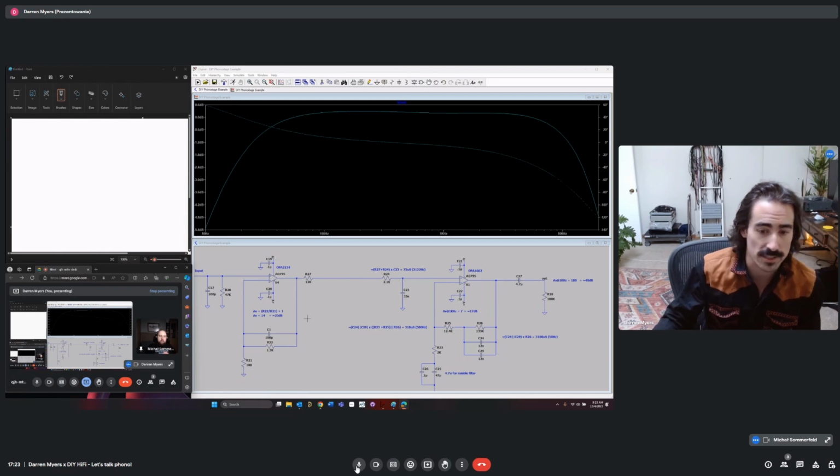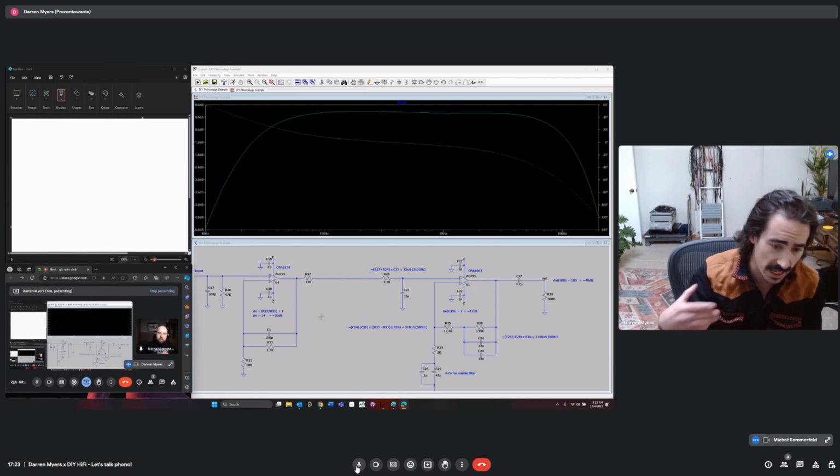If for some reason this is very long, like in a power amplifier, where you have to bring it back quite a ways, you could put in a little isolation resistor, like 10 ohms or something like that, right where you bring the feedback back, and that can isolate that trace capacitance and reduce the chance of oscillation and creating a condition of instability in the amplifier.